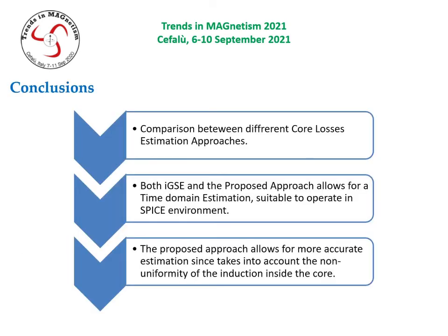So, to conclude, in this paper, a comparison between different core loss estimation approaches has been proposed. Both the improved generalized Steinmetz equation and the proposed approach allow for a time domain estimation, which is a suitable solution to operate in a SPICE environment. And finally, the proposed approach allows for more accurate estimation since it is able to take into account also the non-uniformity of the induction inside the core.